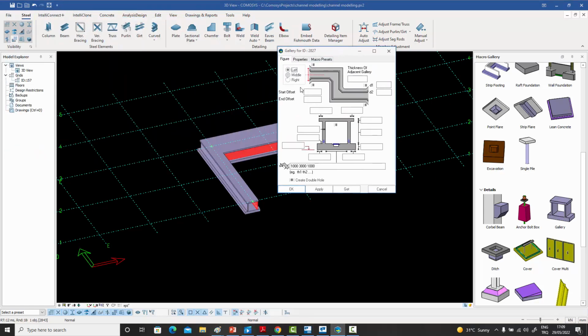So this kind of control you have from there. You can obviously change the points around which it's anchored. Using those parameters, you have complete geometric control, as you see, over the size of the gallery, etc. You even have options for starting the widening of the gallery at the start, at the end. It's very easy to see that doing this manually with 5 or 6 wall commands will be time consuming.